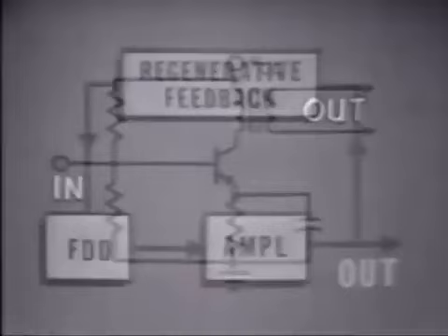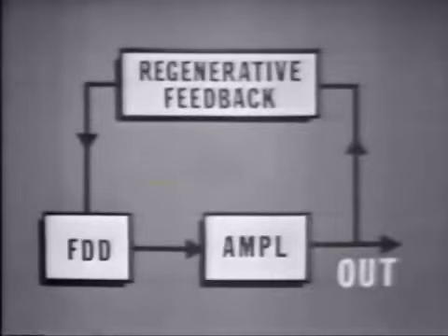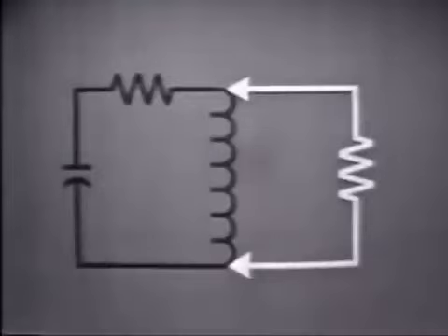And thus we see the need for a frequency determining device. In this case, the LC combination. These component values are carefully calculated to oscillate at exactly the right frequency. Then the exact amount of feedback. And we have an LC oscillator that provides a signal of constant frequency and amplitude. One other